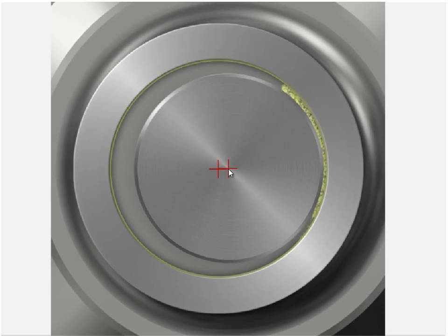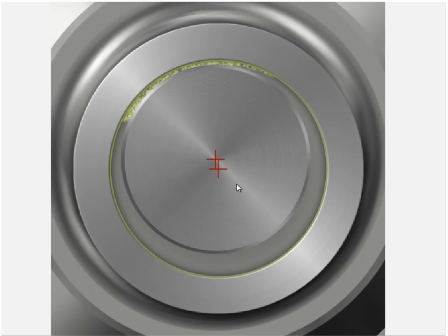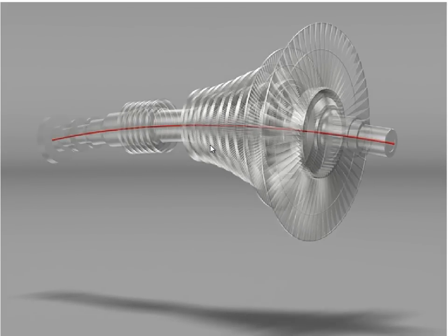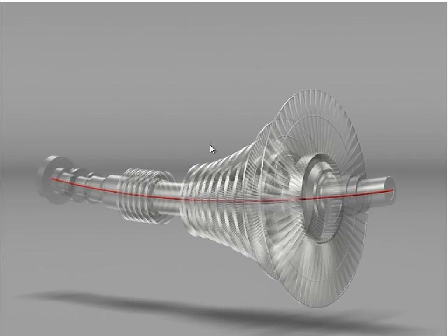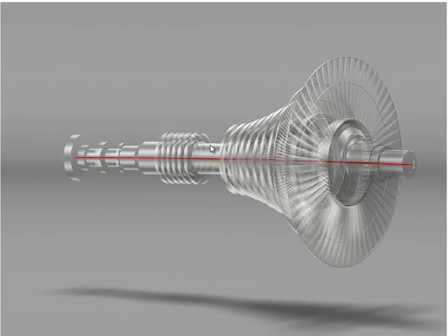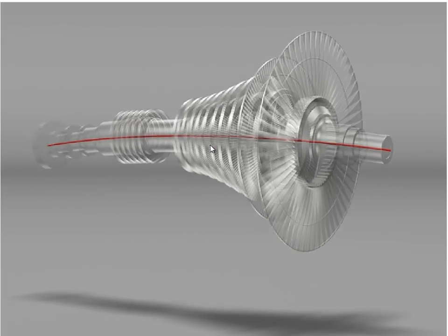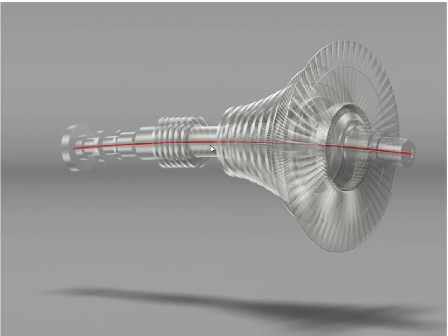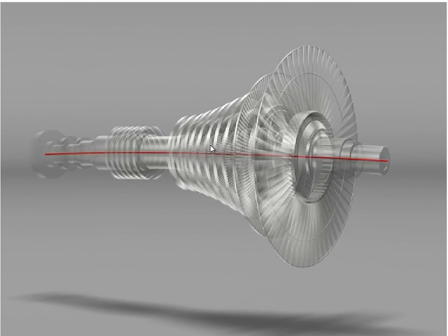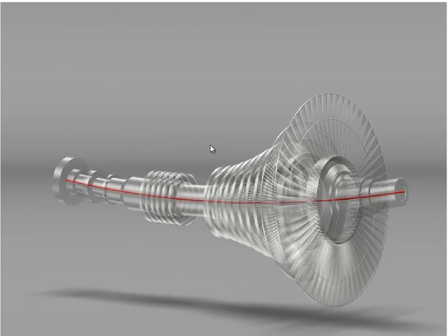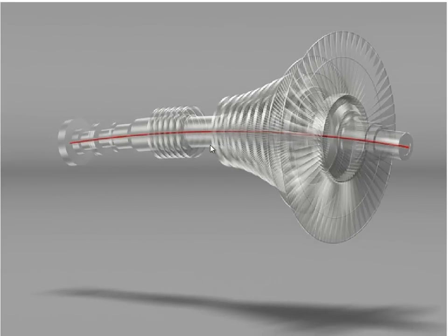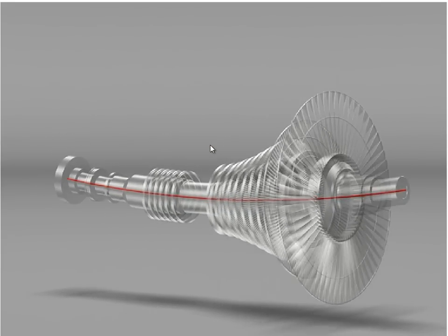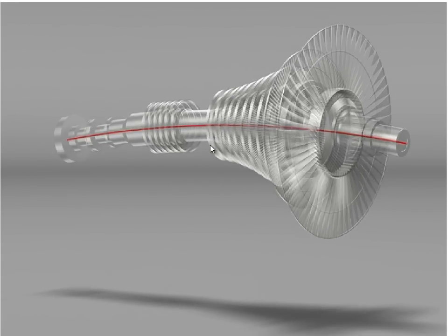We want to know in essence what the shaft is doing, what the center of the shaft is doing, because there are other faults in addition to unbalance and misalignment and preload and these sorts of faults. We're interested in the rotor dynamics as well, particularly as we go through the critical speeds. So in this instance, exaggerated, but that's the motion at the first critical, let's say. A lot of detail we could go into, but I'd be interested in how do I take measurements to tell